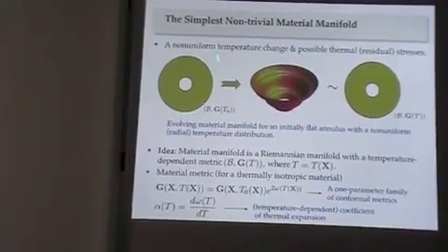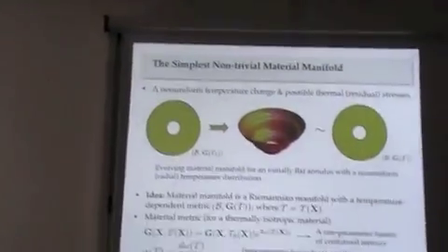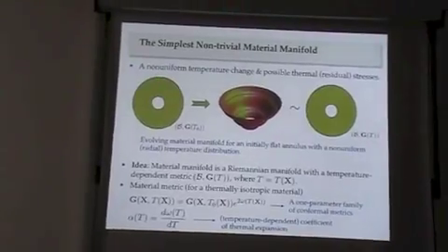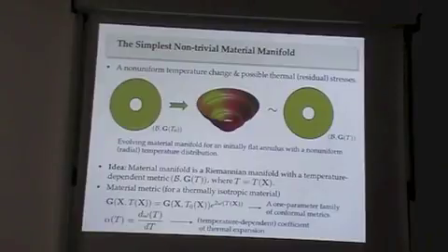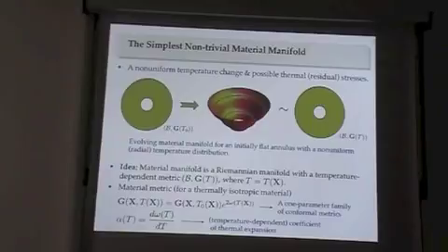So if I give you an unstressed body a uniform increase or decrease in temperature, and if this body is free to move, it would expand or contract without any residual stresses, right? Now, if I give it a change in temperature which is axisymmetric, it would like to go to the third dimension like this to stay stress-free. If it cannot, it would have residual stresses, right? Now, let's say I have to stay in 2D, so this would have residual stresses.